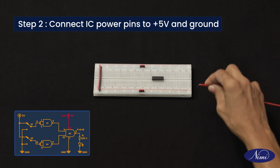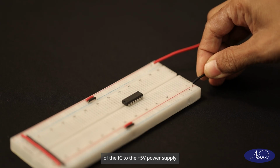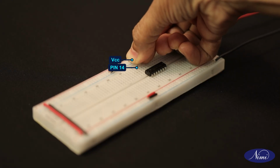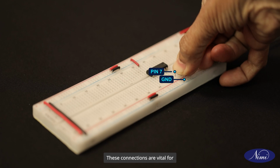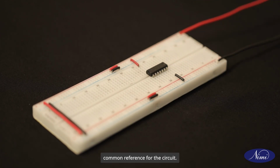Connect linking wires from the power supply to the breadboard. Next, connect 14th pin of the IC to the plus 5V power supply. This is our VCC, the lifeblood of the IC. Then, make sure pin 7 is connected with the ground. These connections are vital for providing the necessary power and establishing a common reference for the circuit.